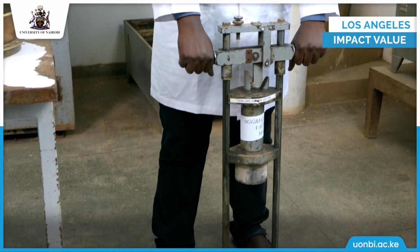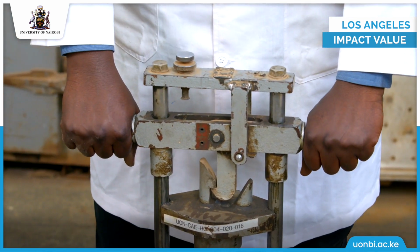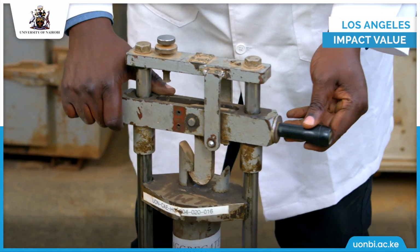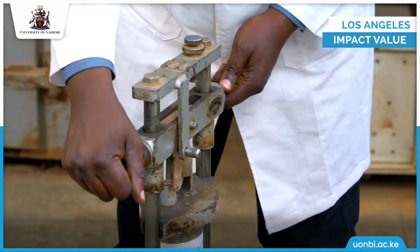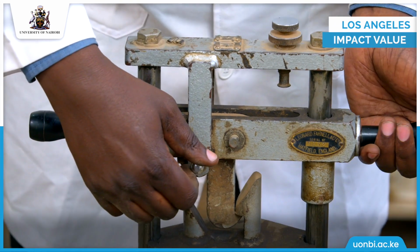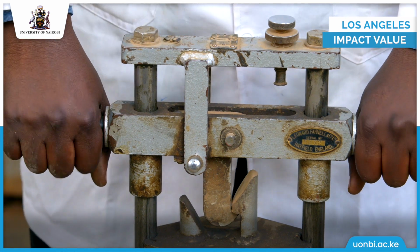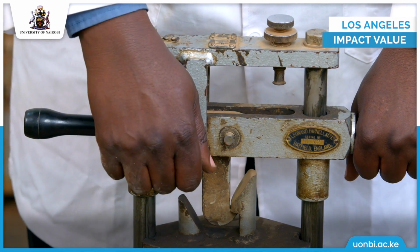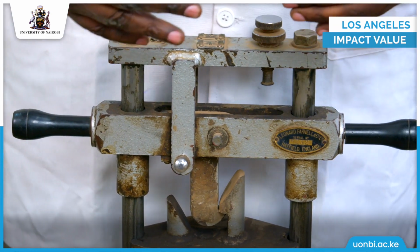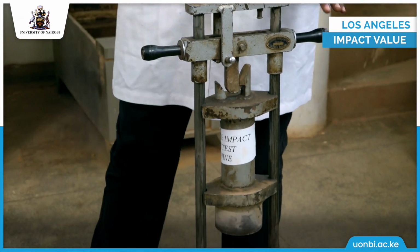We have the handle that we use for handling the experiment. And of course, there is a safety pin. This is the safety pin. Once the safety pin is removed, you slightly raise the hammer and remove the safety pin. When the safety pin is removed, then the hammer will fall freely. And the height of fall in this case is 380 millimeters.